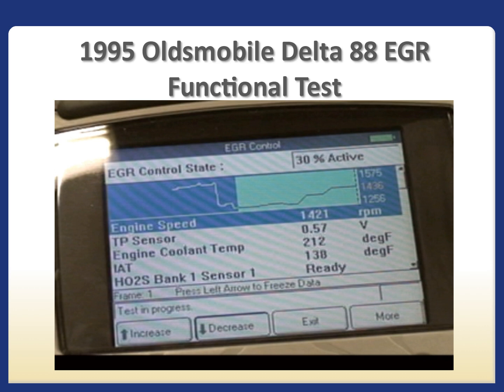Carefully watch the digital readout. The areas marked with yellow arrows in this photo display the EGR opening as a percentage, the engine RPM, and a graph shows the RPM drop. Regardless of the scan tool used, the result should be the same. The EGR valve is cycled open, the engine RPM should drop, and the engine idle should become rough, indicating the passageways are clear.